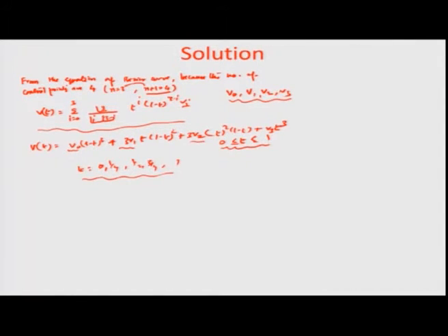Let us say when we do for V 0, you know that V 0 has the coordinate value 0 0 0, because this is the first point, and typically the Bezier curve's first point also passes through the point which is outlaid across both ends of the curve, that is V 0 and V 3 in this particular case. So, we know V 0, we need to find out what is V of 1/4, and for doing that we first put only the x values.